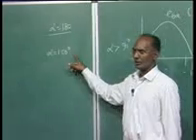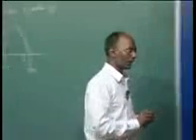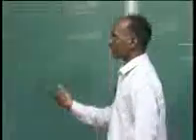Now, I want to draw the output voltage corresponding to alpha equal to 150 degrees. You have to see where alpha is. I start at omega t equal to 0 at the beginning of this graph. This is 180 degrees, this whole cycle, so here is where alpha is 150 degrees, because this portion is 60 degrees.